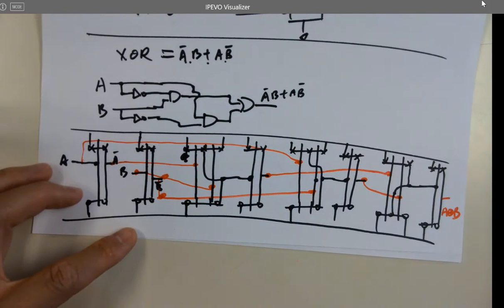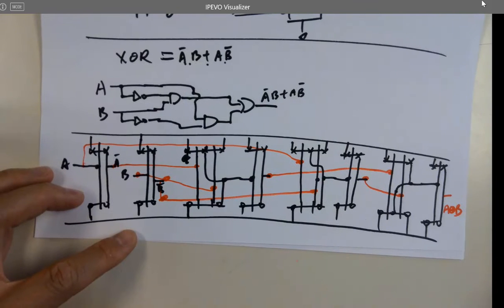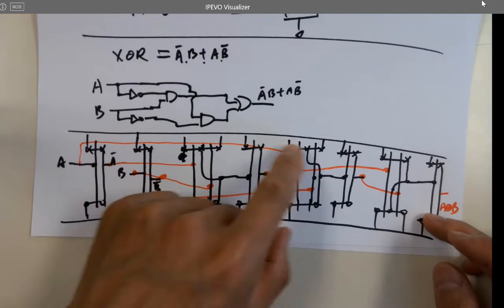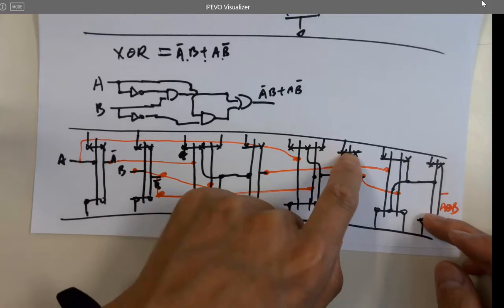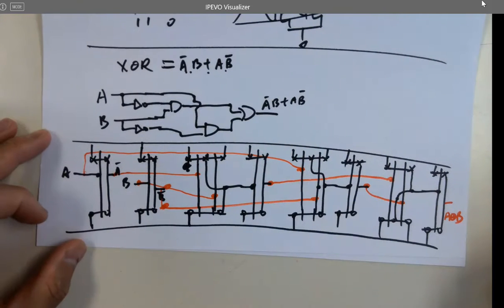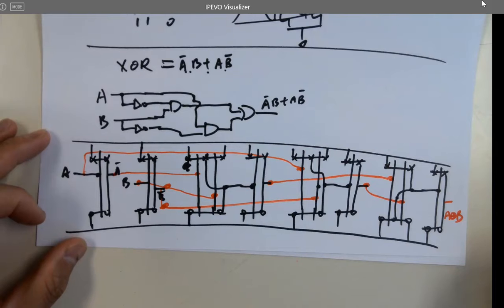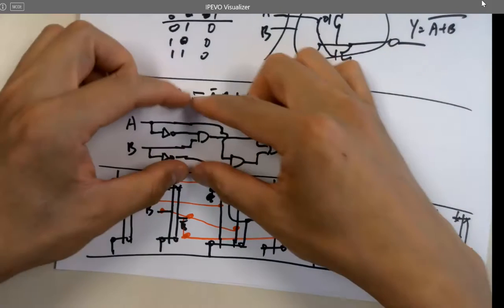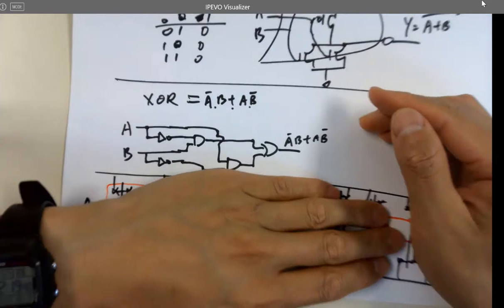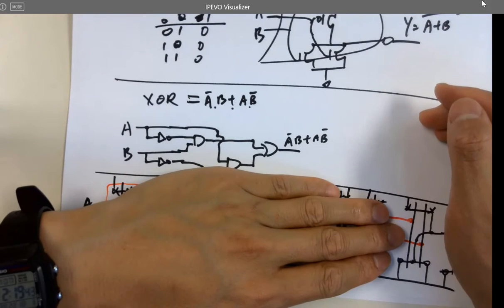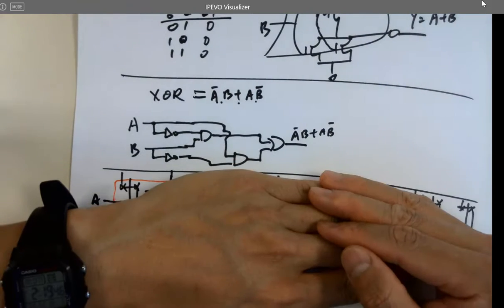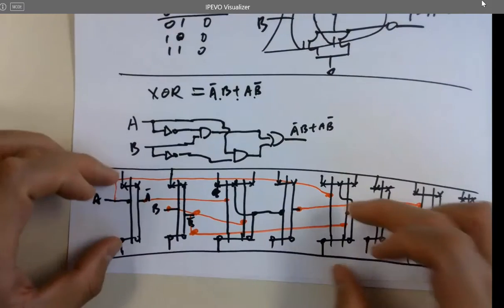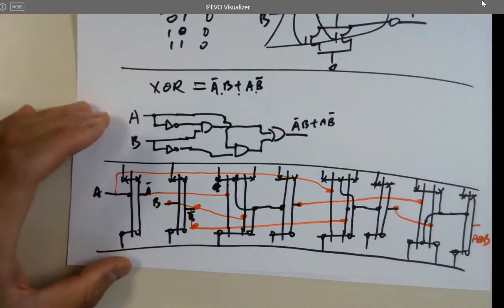Transistor count for that: 1, 2, 3, 4, 5, 6, 7, 8, 9, 10, 11. Yeah, 22. All right, let's see how big then. Now you see why we need stick diagrams? Because you open up the layout and you just look at this. Could you lay it out? No. I want to know if I could lay it out with just this. No, you couldn't, even with this. Yeah, so when you draw these, I highly recommend you use a different